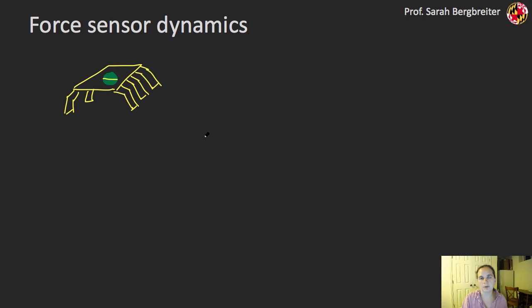So another example is from my own lab. We're trying to make a little robot jump. And so one of the ways we did this was a robot that was about 4 by 4 by 7 millimeters. It had a little piece of energetic material in the middle and a little wire patterned on top of that energetic material. And when you shoved a current through it, it heated up the energetic material enough to initiate a reaction. And when you did that, you got a lot of thrust out of that pixel of energetic material, and the robot would jump.